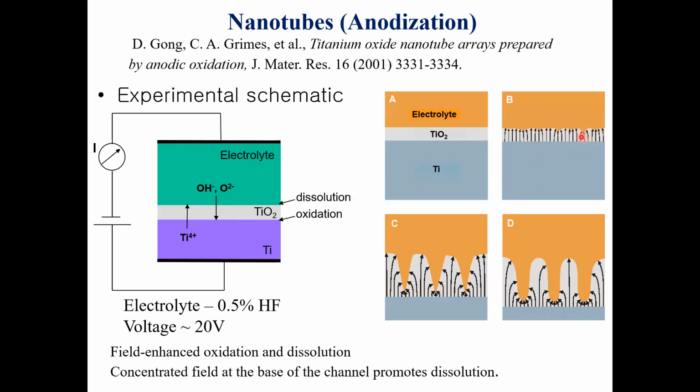And as you create the etching site, the electric field is highly concentrated in the valley here, right? And the drilling of the etching becomes anisotropic. So it will be etching more and more material from the tip of the hole than from this part of the oxide. So you can eventually see that it's anisotropic drilling. So you're basically going to create this hole and keep this material in between the holes.